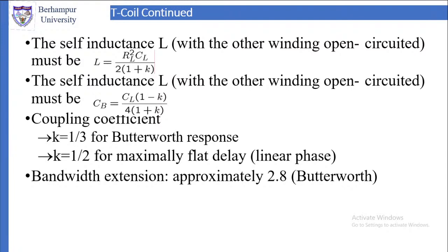Now what will be the coupling coefficient for the inductors? The coupling coefficient will be equal to 1 by 3 if you go for a Butterworth type of response, and K will be equal to 1 by 2 if you go for a maximally flat delay or a linear phase. Now you may ask me what is Butterworth response, what is maximally flat delay or maximally flat response.